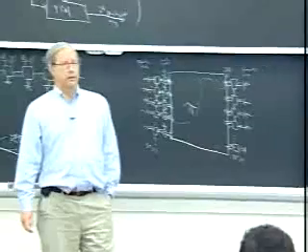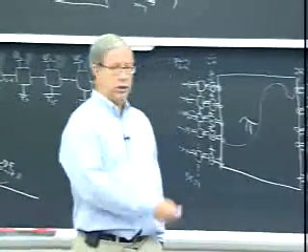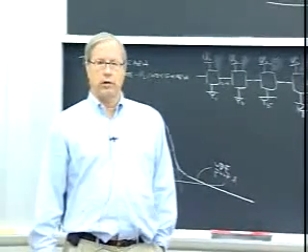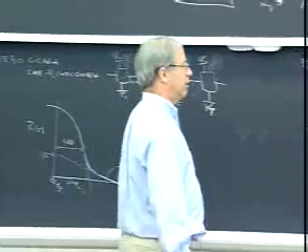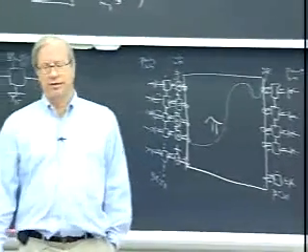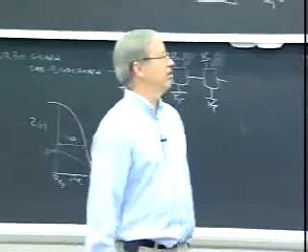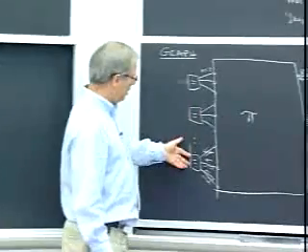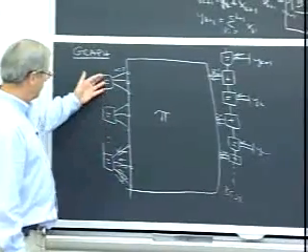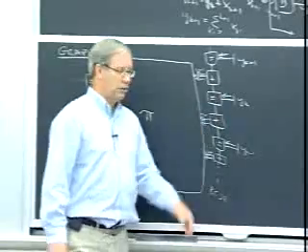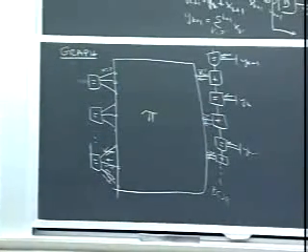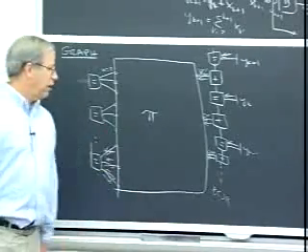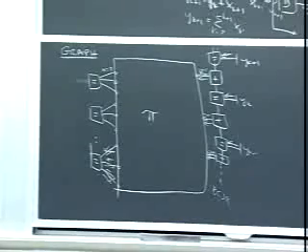Now, does this work as well as either of the two previous ones I put up, low density parity check or turbo? Not quite, but it works amazingly well. This is the moral here, that even this incredibly simple code, where nothing is going on, where all we have is binary state variables, we have equals and zero-sum nodes. That's it. It's made out of the simplest possible elements. Even this code can get within a dB or two of channel capacity.